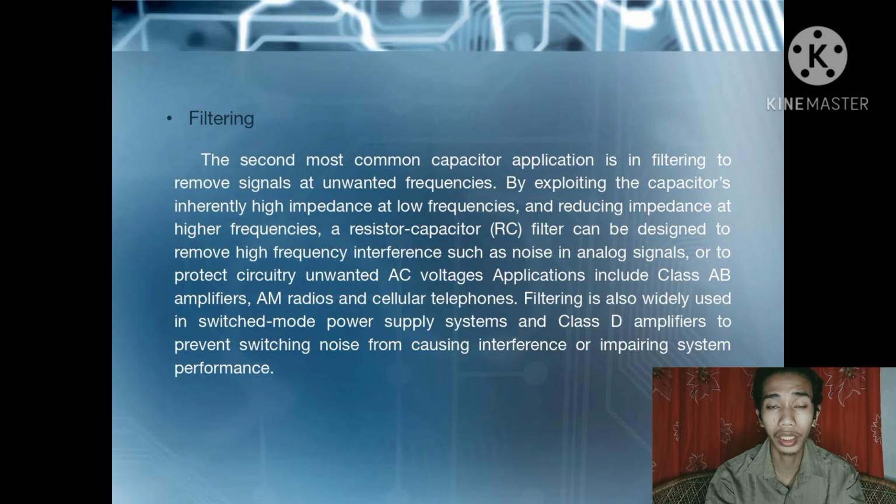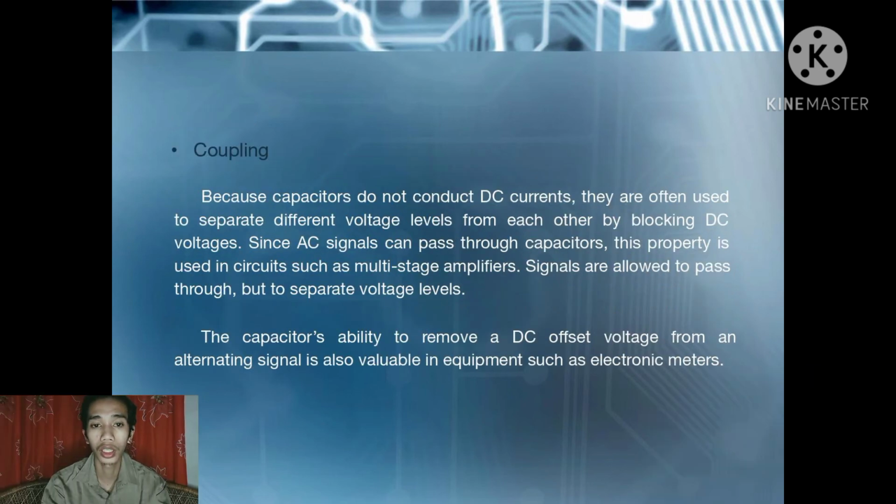Filtering is also widely used in switch mode power supply systems and Class D amplifiers to prevent switching noise from causing interference or impairing system performance. So that would be the use. The second most common application for capacitor, the filtering. Next one would be coupling.